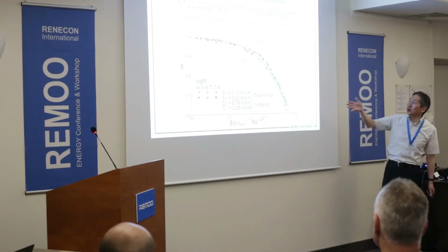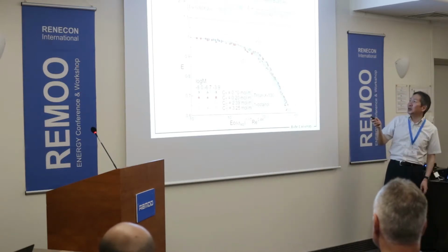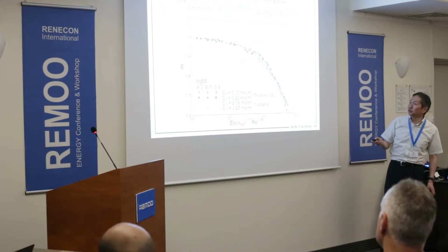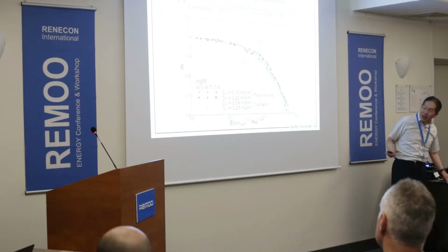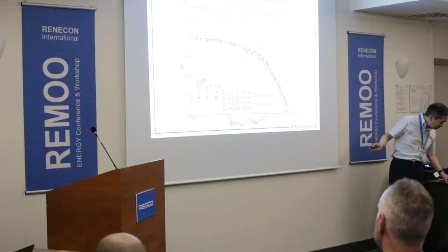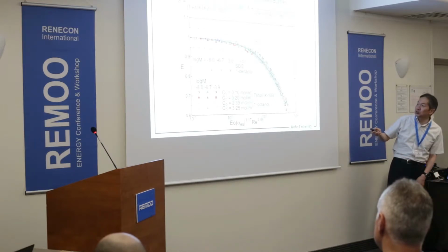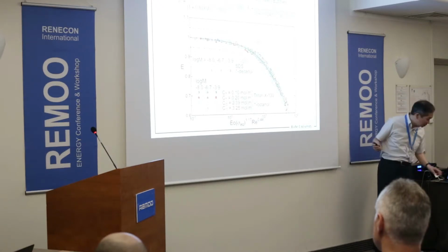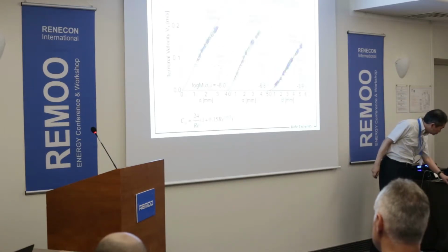Anyway, you can also obtain a very nice correlation, the same correlation, for the contaminated bubbles. This is for a different surfactant and different Morton number system. And after making this, we obtain this kind of data using two different surfactants, obtain this correlation. After that, we did an experiment using two additional surfactants, and all the data follow a single line, so that also for the fully contaminated system, you can use this correlation, the more or less similar correlation.